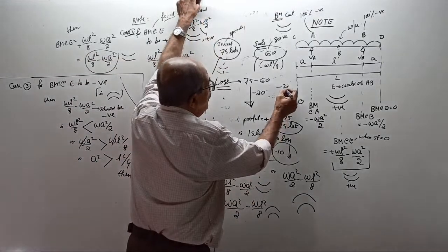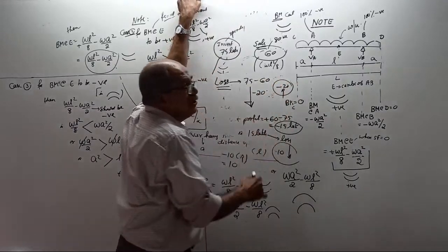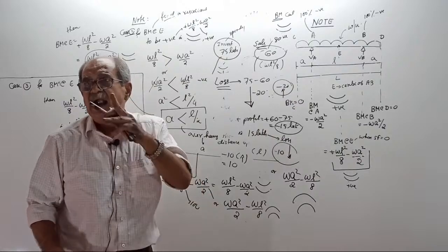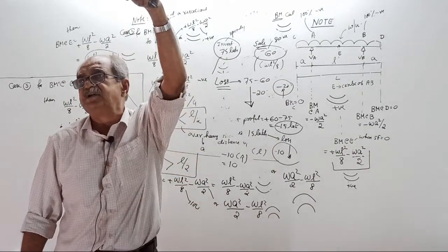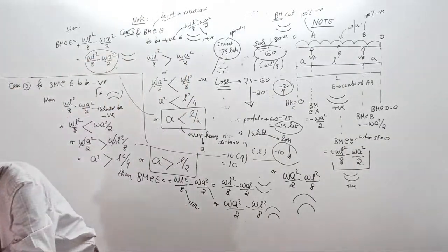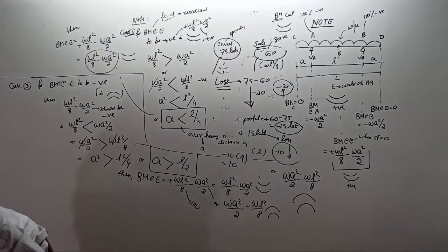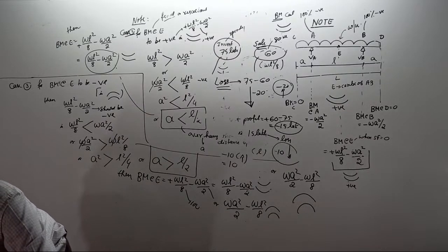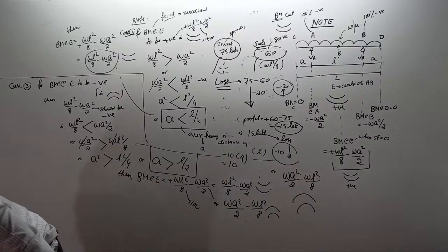Upward is positive, you type minus 20. So if you type minus 20 with upward positive, STAAD.Pro should show a load downward of how much? Tell me. How much? You apply minus 20, upward positive. So in the diagram, STAAD.Pro should show that load in what direction?